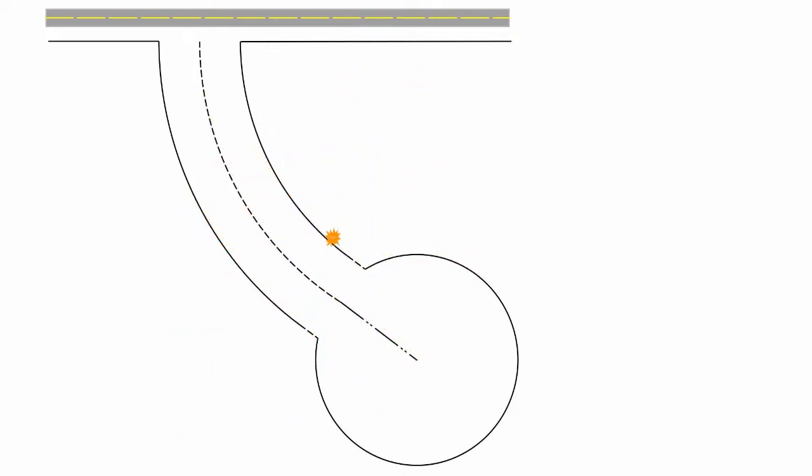Optimum design for the road indicates a delta angle to be 54 degrees 10 minutes 10 seconds for the center of the curve, starting at the existing edge of the right-of-way and going to the tangent extension for the cul-de-sac. The center of the cul-de-sac turnaround is located on a forward tangent to the center of the curve. The layout of the cul-de-sac that is shown does not include any transition curves.